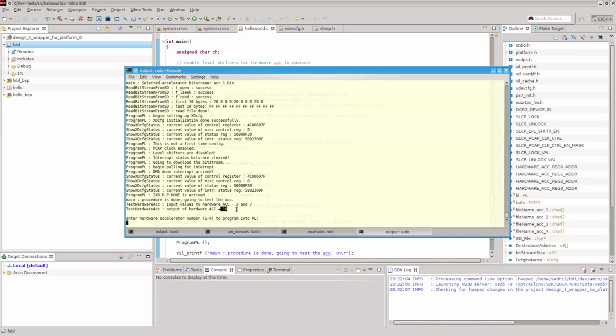So as you see, our system is working, our implementation is working. Our implementation is stable, so it doesn't crash, because maybe you write a program and then it reconfigures the PL for the first time and it never reconfigures the PL again. So this is why it's extremely important that before you begin reconfiguring the PL, first make sure that the PL is out of its previous configuration state.